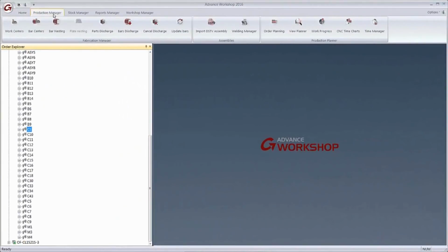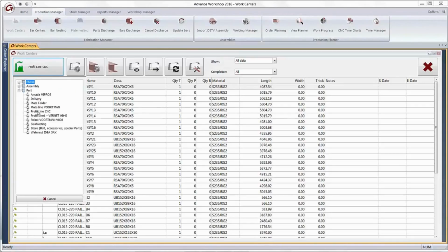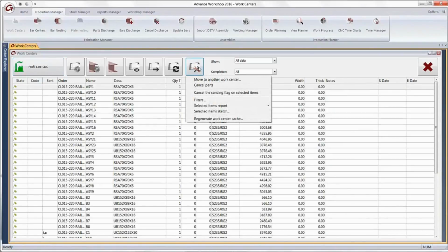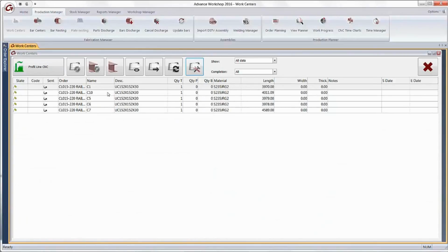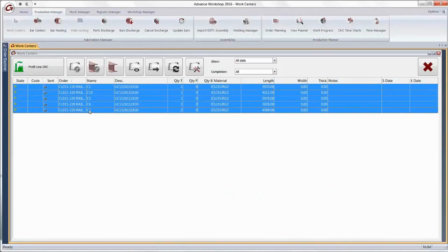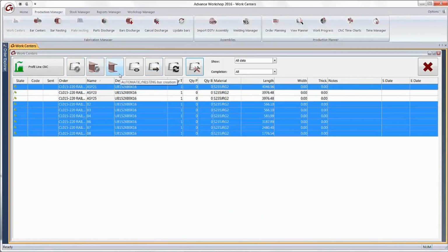Based on the type of weld, assemblies will be allocated to a certified welder appropriate for the weld required. Then the assembly will go for sandblasting and then painting before marked for delivery or allocated to a subcontractor for a special finishing. If we take a look at jobs pre-allocated to a dedicated work center and filter a particular section, as a production manager we can authorize a job, create and send a works order, or make adjustments to the nesting if required.